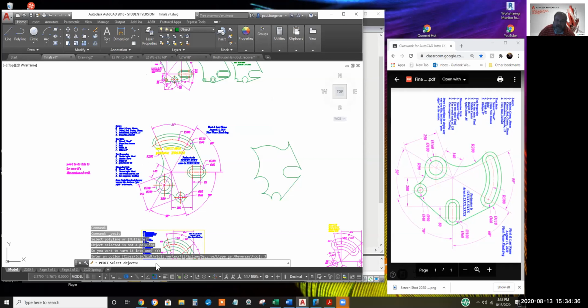Now it says select objects you want to weld. It's tempting to click all the way around all 13 remaining pieces, but being incredibly lazy, I'm just going to window them all with a crossing window. And there's no harm done if you over select. Only those objects that are joinable will be worked on. It will be welded to the original.